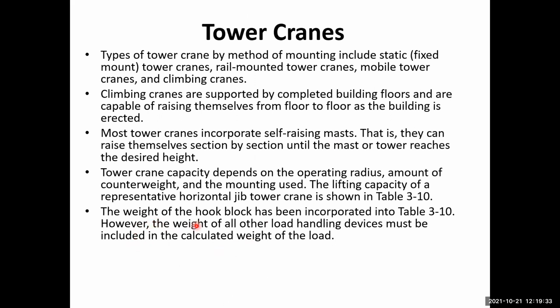Okay, so the weight of the hook block has been incorporated into table 3-10. However, the weight of all other load handling devices must be included in the calculated weight of the load. So it is also important that when we say this much is the capacity of the tower crane, we should be very clear what types of loads are included in the capacity.